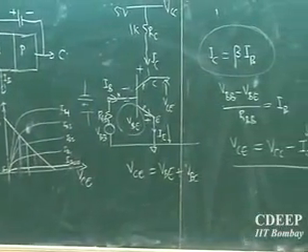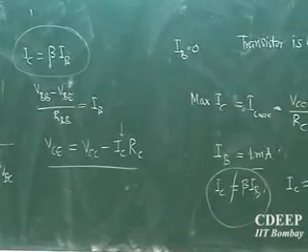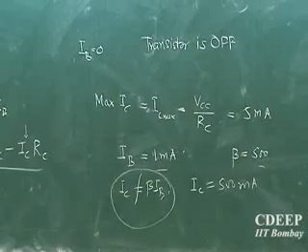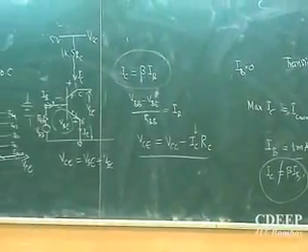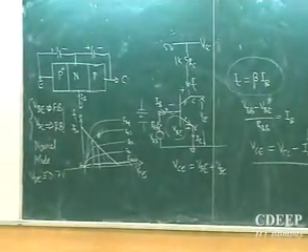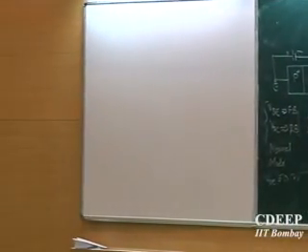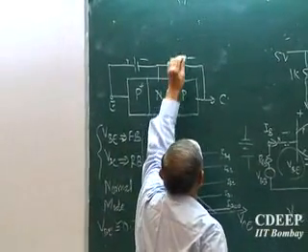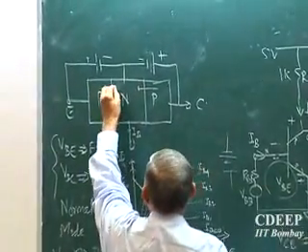So one always sees that the base collector junction and base emitter junction both get forward bias, though externally we are still putting it reverse bias, because for a PNP the polarity is kept otherwise. Is that clear to you? So this is a very interesting thing that happened. The device internally got the opposite polarity. Is that clear? That means both junctions are forward biased, and you can see what it can do then. If both are forward biased, this will inject, and this will inject.